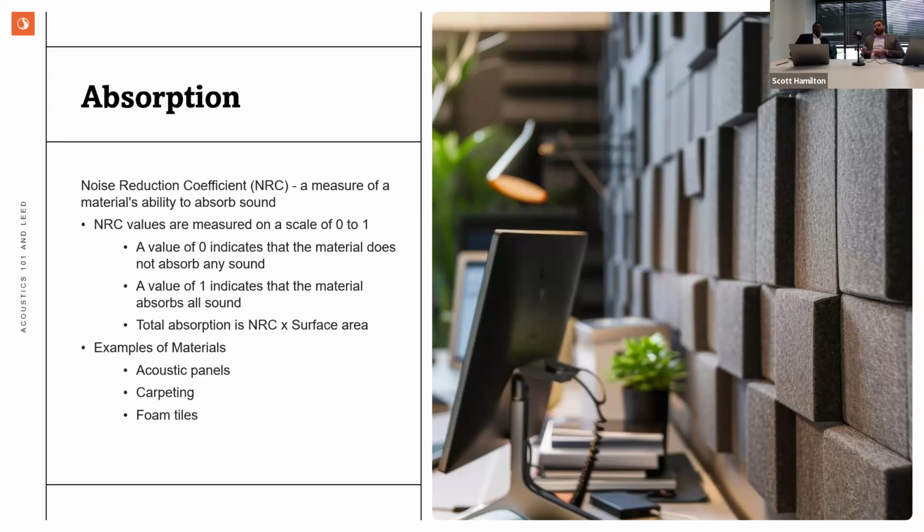You'll see carpeting is often misconstrued as an acoustically absorptive material, probably because we all moved into an empty apartment and rolled out the rug and suddenly the room calmed down. Generally, carpet tile on concrete is like an NRC 0.2, not very absorptive, has some properties, it's better than bare drywall. And then the last one you'll see a lot of is acoustic foam. Everyone's image is acoustic foam, that triangle stuff. We often try to avoid it because we've all seen when the bad foams get installed or the fireproofing wears off, they tend to be an unsafe material. So we work with acoustic materials that give us that high absorption, but also play better into fire ratings and high wear and tear. If it's a high touch environment, can it handle abuse resistance, all those kinds of things that factor in.